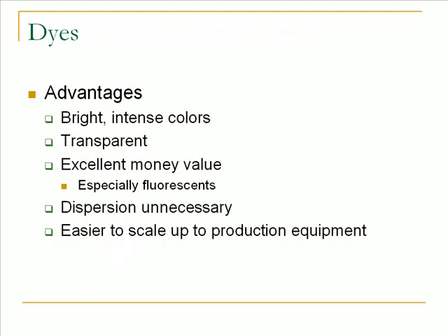In the lab, we have maximum loadings for different kinds of colorants. For the inorganics, maximum loading is 0.5%, which is the highest value. Inorganics are the weakest. Organic pigments are 0.25% maximum loading, and dyes are 0.1%. So dyes are very strong, so you don't need very much.